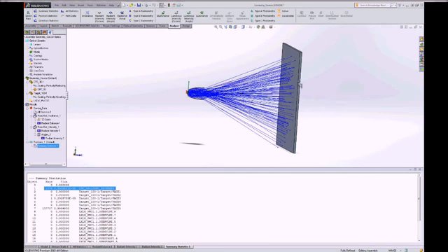Now, I think we can all look at this and we know that this must be what is internally thought of as phase 6, but maybe in some instances you're not quite sure which particular surface it is you want to analyze based on this information. But if I come down here, I can select it and just say highlight surface, and you can clearly see visually indicated which surface it is on which that information is being provided.